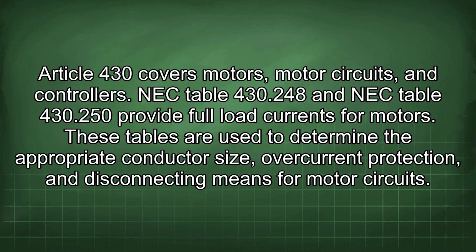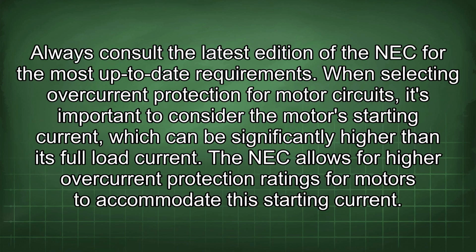NEC Table 430.248 and NEC Table 430.250 provide full load currents for motors. These tables are used to determine the appropriate conductor size, overcurrent protection, and disconnecting means for motor circuits. Always consult the latest edition of the NEC for the most up-to-date requirements.